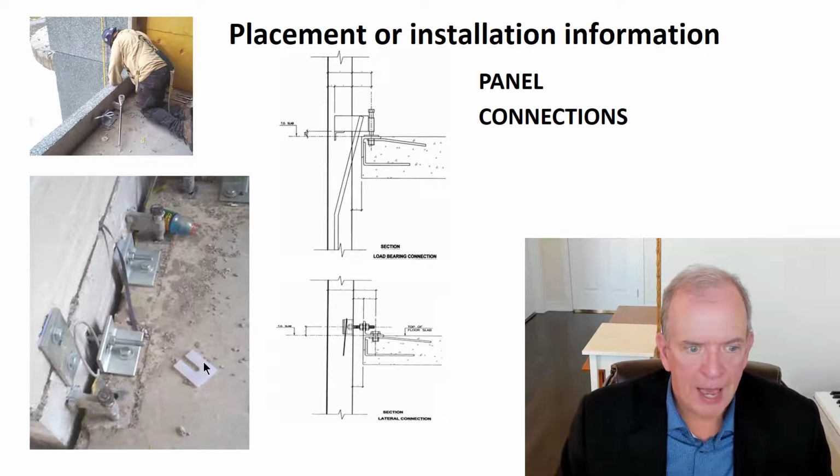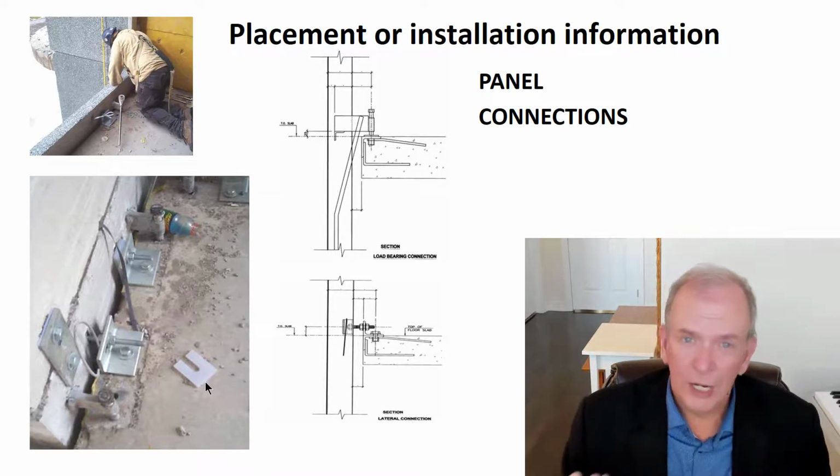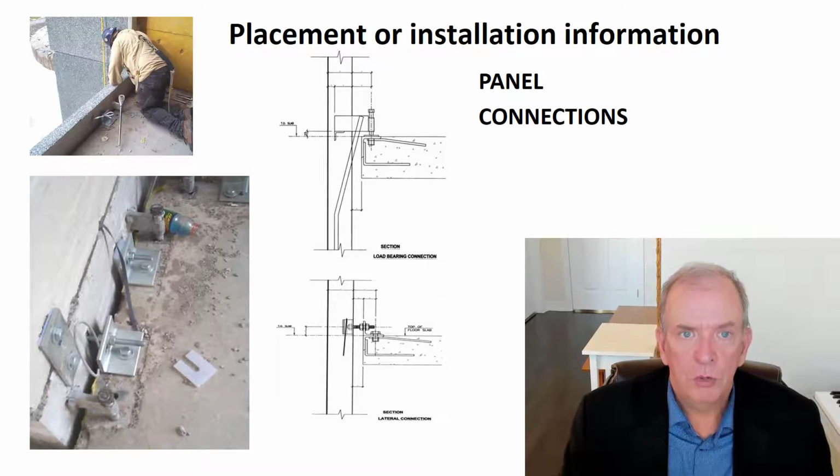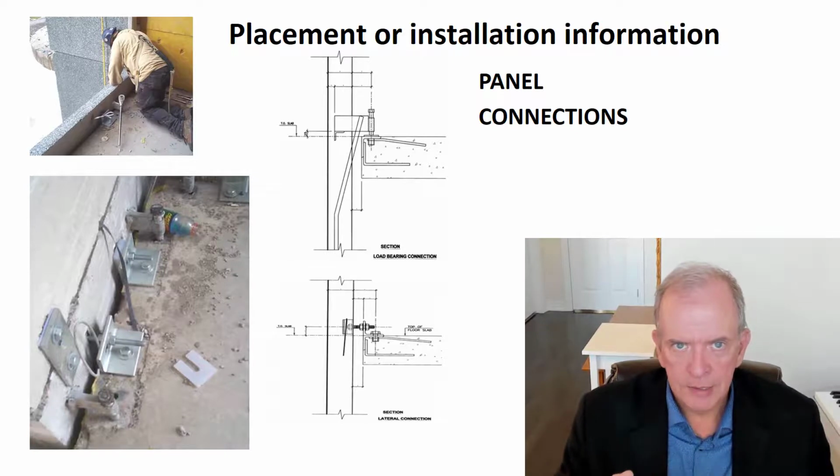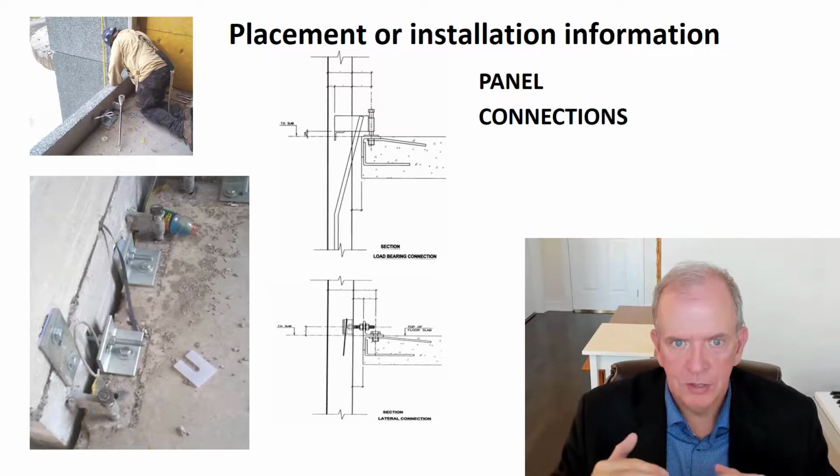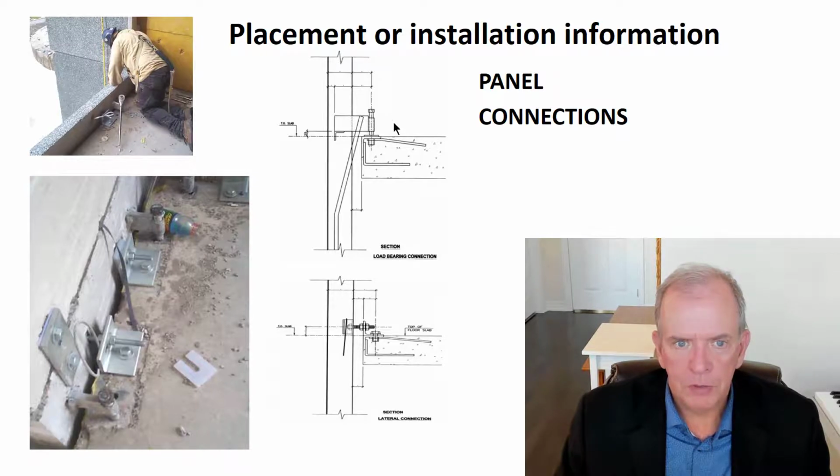And these are like packing pieces that go in between when you have to make adjustments, right? So the different packing pieces. So this is an example, just one example of the types of shop drawings that need to be done and reviewed before you can order the precast, and also before you can pour your slabs, because then you're going to want to know all the detailed information about the placement of these anchors, so that they'll be able to support the direct loads from the panels.